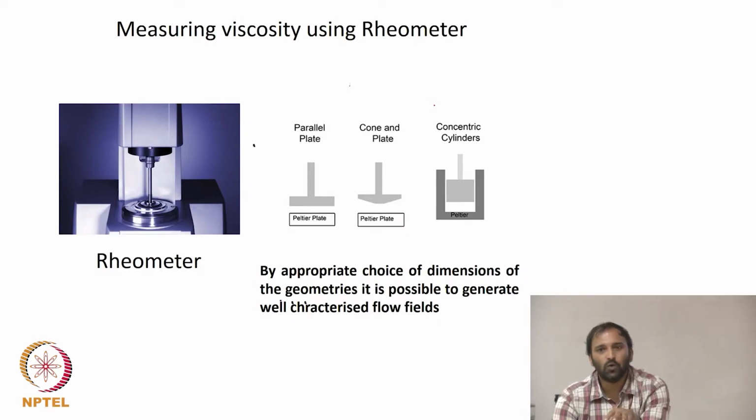Now when you work with these geometries under specific conditions, meaning if you choose geometries of appropriate dimensions, then the flow field that you generate in the fluid in the gap between these geometries is very well defined. And for using rheometers, that is the most important criterion.